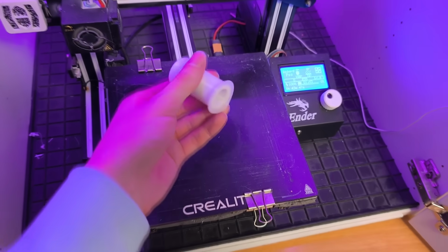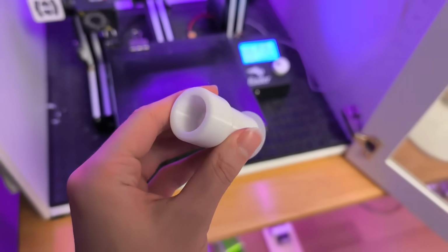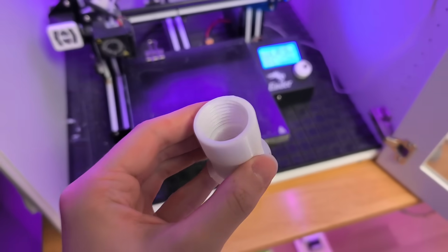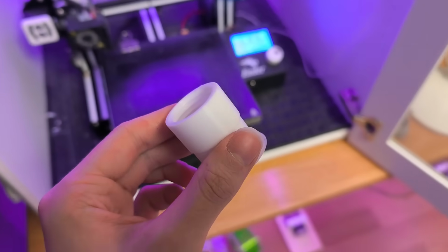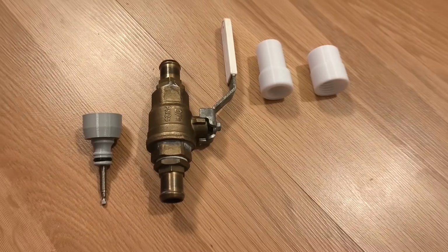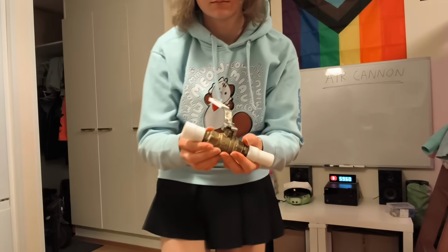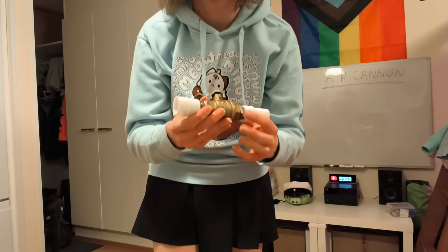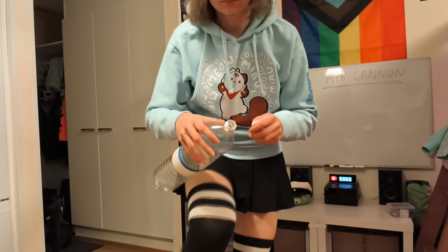I somehow needed to connect the ball valve to the air tank and barrel, so I designed and 3D printed these 2 plastic adapters for it, with deep socket fits over the valve. I glued these with epoxy to the ball valve to get a strong and airtight seal. One end screws onto the air tank, and the other end can be connected to the barrel using some O-rings to seal it, while keeping it removable.